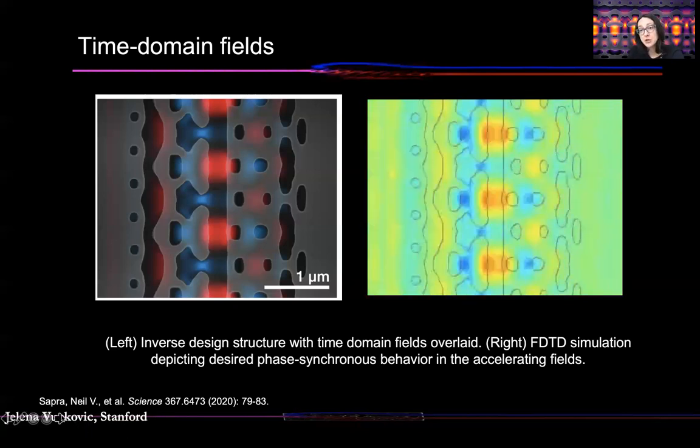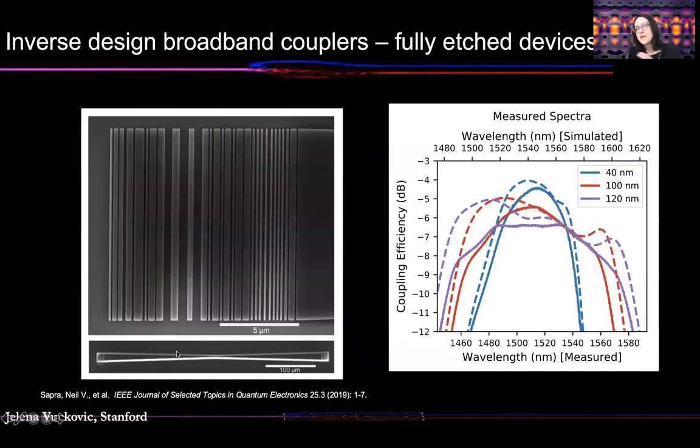So that's the optimization part and inverse design part of the actual stage of the accelerator. And what I'm showing you here is just a single stage of the accelerator, which is 30 micrometers long. It's still 10,000 times longer than in the stage in the traditional accelerators. But of course, you still need to cascade hundreds or thousands of these stages in order to build the full accelerator, which is not a big problem here because each stage is 30 microns long. So in few inches of a silicon wafer, you can stack up sufficient number of them to get to mega electron volt acceleration.